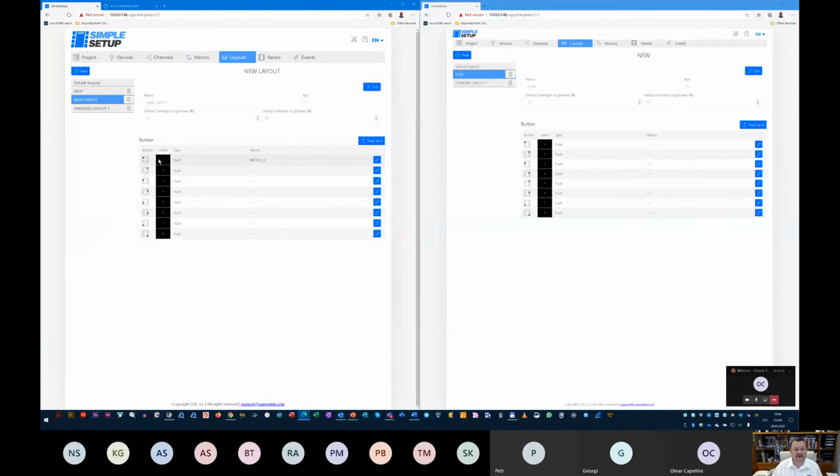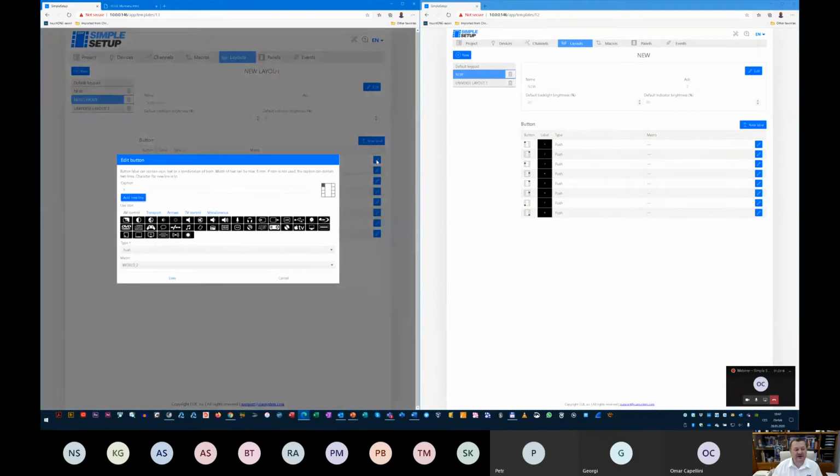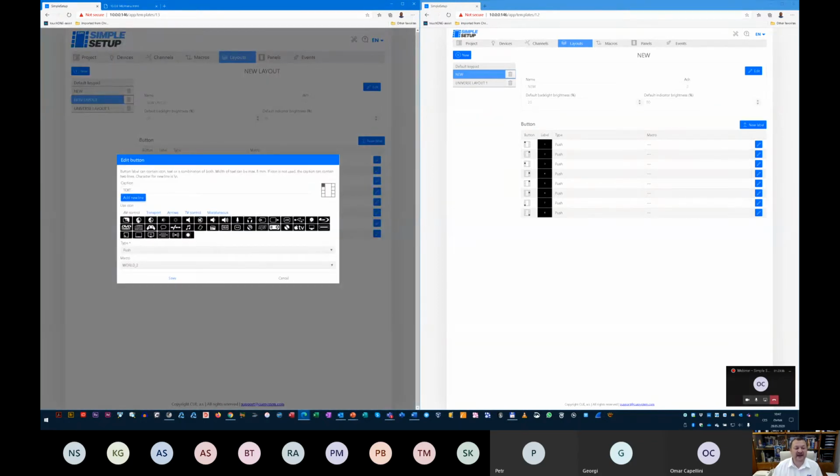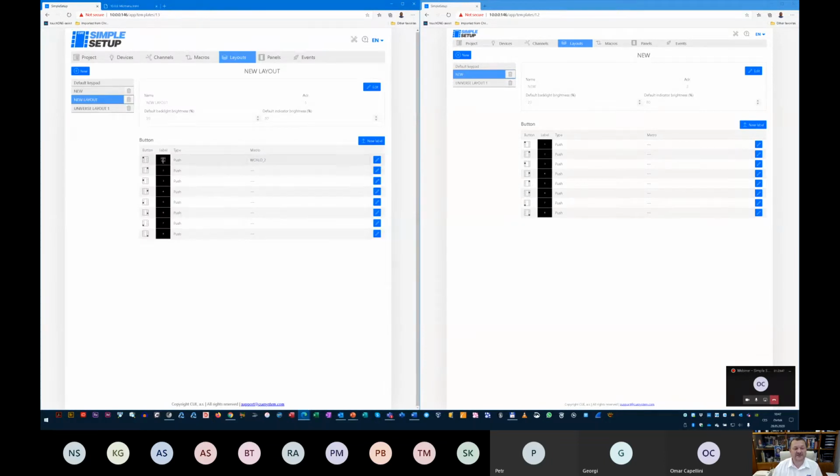And also you need to think about the label, which is this black window in the left part of this section. So you can go back and say, okay, I don't want to use the number 1. I want to use, for example, text instead. Going back, you see there is a text instead of the number I had in the label before. Or you may say, I want to use a text and some symbol, and the symbol should be, I don't know, VGA, D-sub connector, graphics. So I select that, and you see the combination of both.